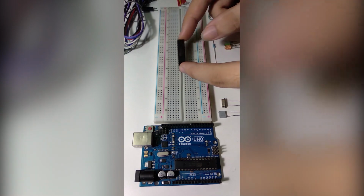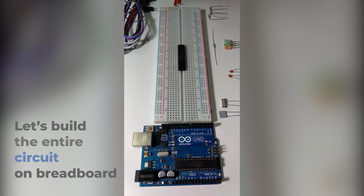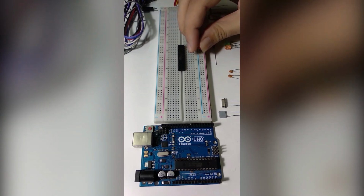Now let's move on to preparing the target microcontroller on a breadboard with a 16 MHz crystal and a 10K pull-up resistor to the reset pin and a couple of other components.